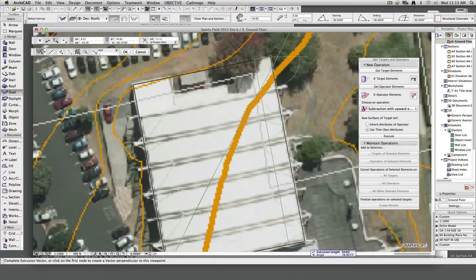Select that, do the length, drag it out. Make sure you're snapping, okay? And make sure you're snapping to the right side of the wall as well. You want it to go from the outside edge down to the outside edge. Make sure you're not going from the outside to the inside, because then it'll be on a funny angle.